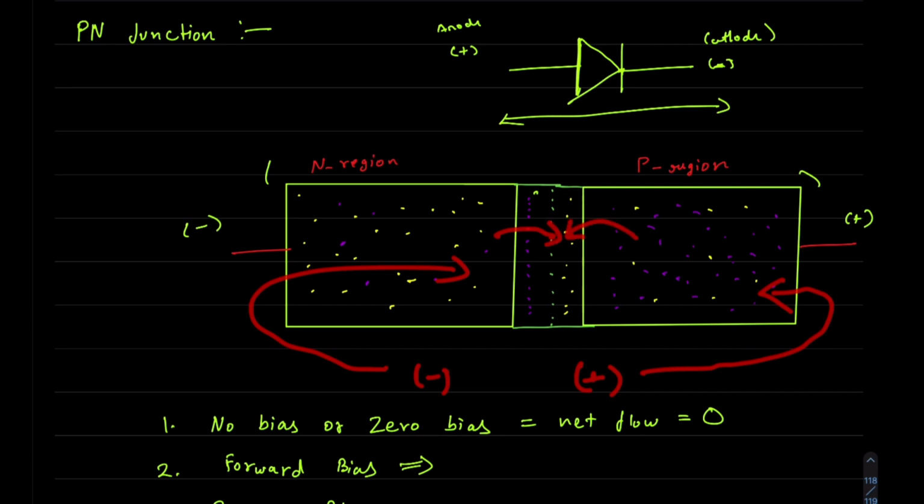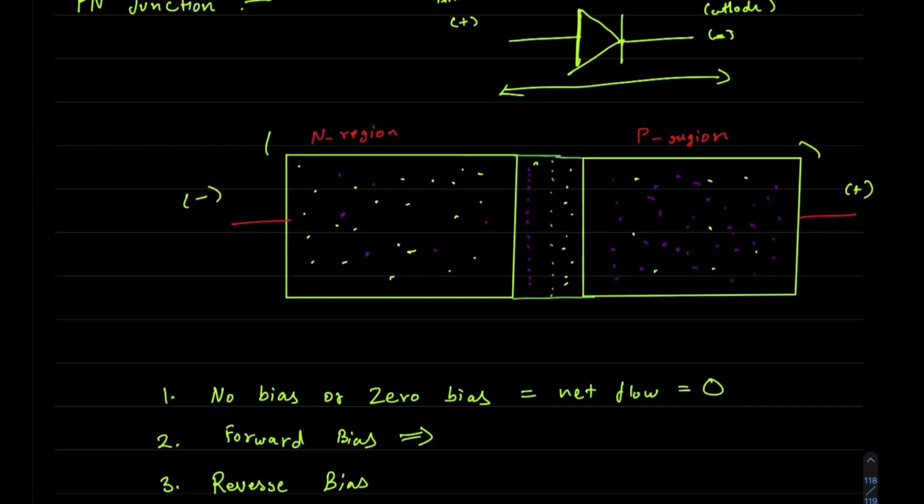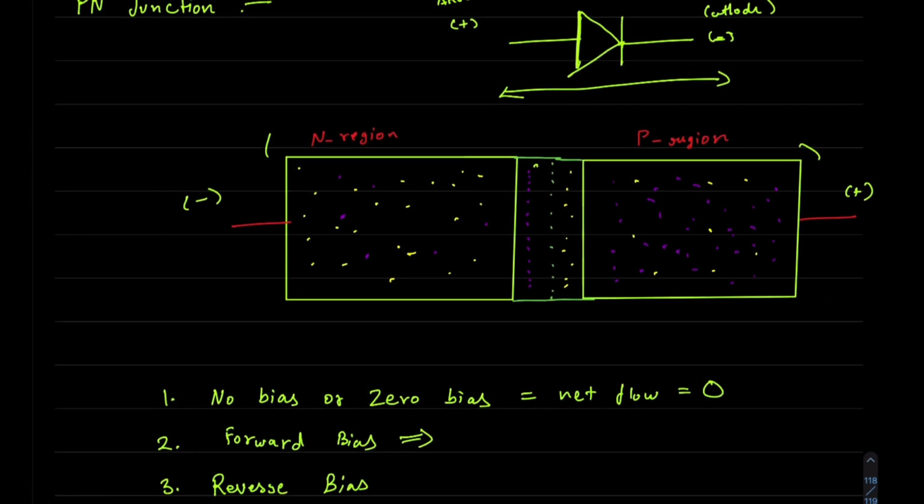They start crossing over the depletion region, and this results in a characteristic curve of zero current flowing up to this voltage point. Up until this voltage point, 0.7 or 0.3 or any other voltage, is reached, there will only be zero current. But after that, high current through the diode will start moving with little to no increase in external voltage, basically.